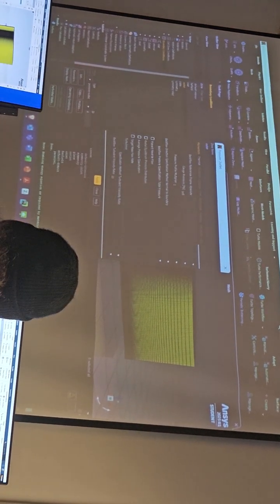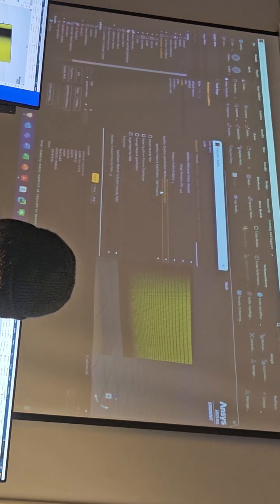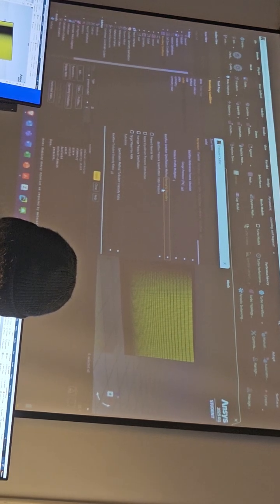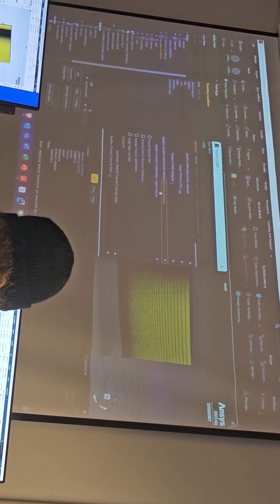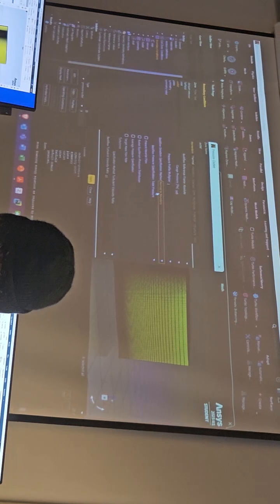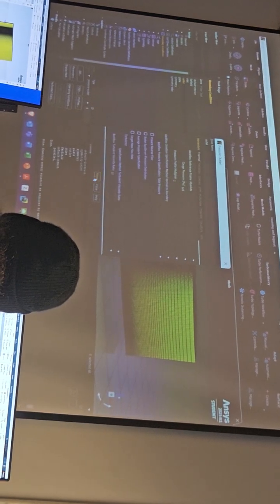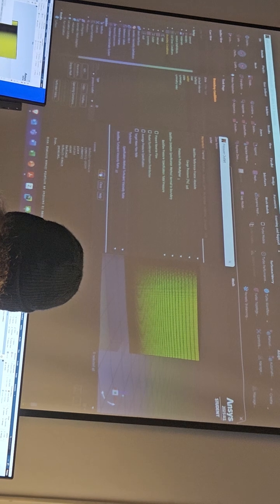And that's it. Other boundary conditions are for backflow. So if in case there is some flow that is going in the negative direction, that's not our case, so we don't really need to care about these backflow boundary conditions. And apply.